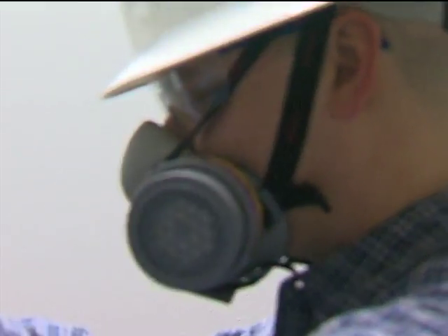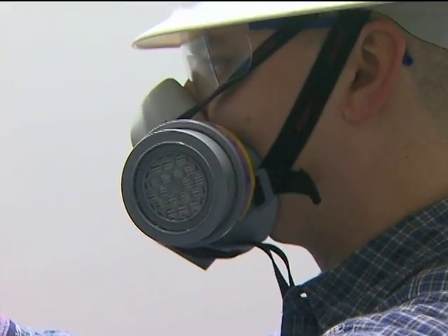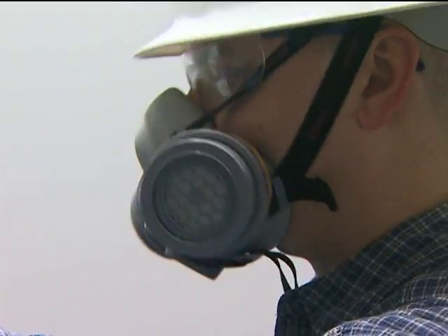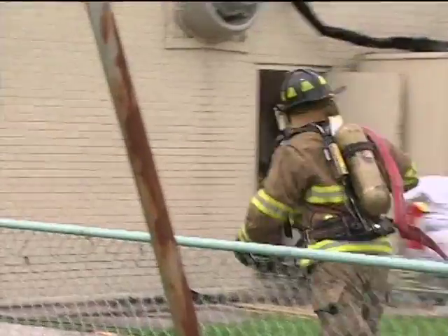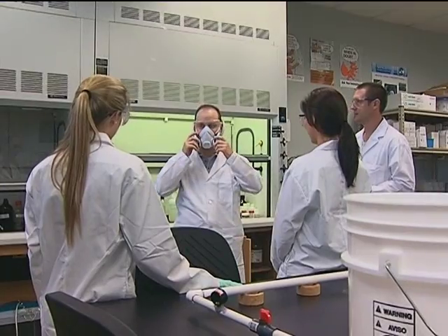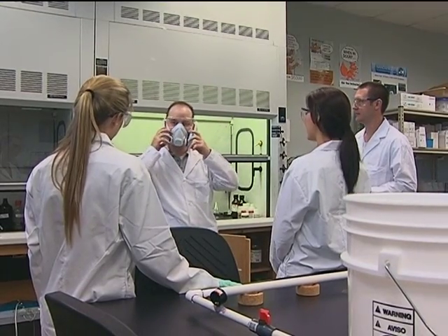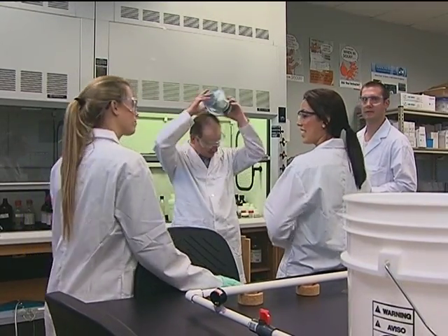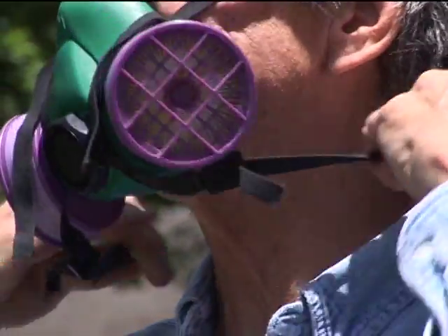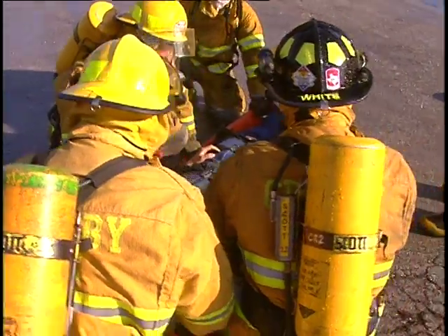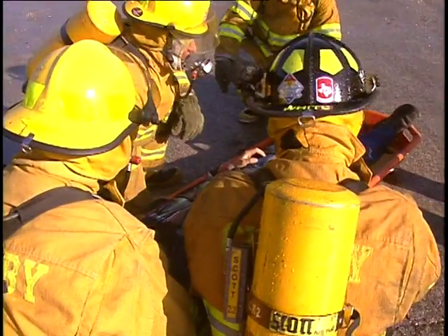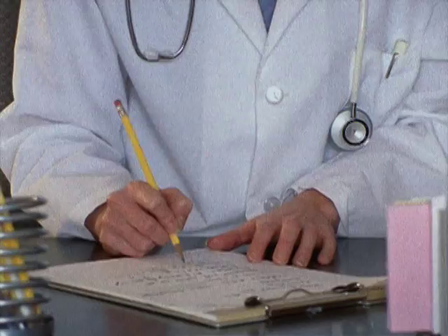Using a respirator may place a physiological burden on employees. The effects can vary with the type of respirator worn, the job performed, workplace conditions, and the medical status of the employee. Some conditions may adversely affect the health of employees who wear respirators and include negative pressure respirators, which restrict breathing, self-contained breathing apparatuses, which are heavy and bulky, and some respirators can cause claustrophobia.